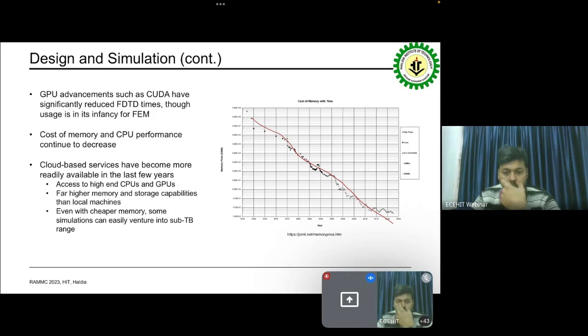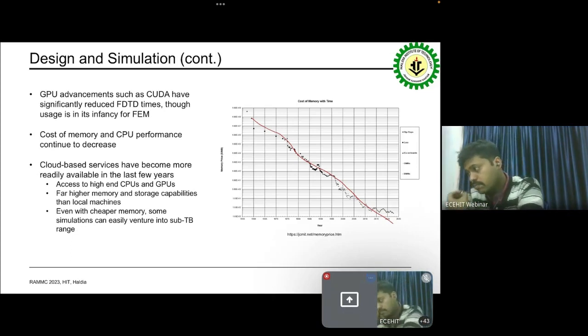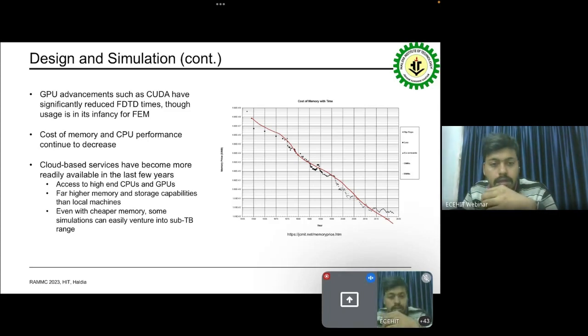The customer will come to us and they will say, okay, I want device X to do this particular application, but I need to know what it's going to look like when I have it mounted to the coplanar waveguide on my PCB. Can we put in any compensatory structures to help to offset those launches on the PCB? Can we get a good impedance match? Is it going to cause any issues with anything coupled next to it? Radiated fields, near and far fields, both coming off of the device, is that going to cause any potential issues?